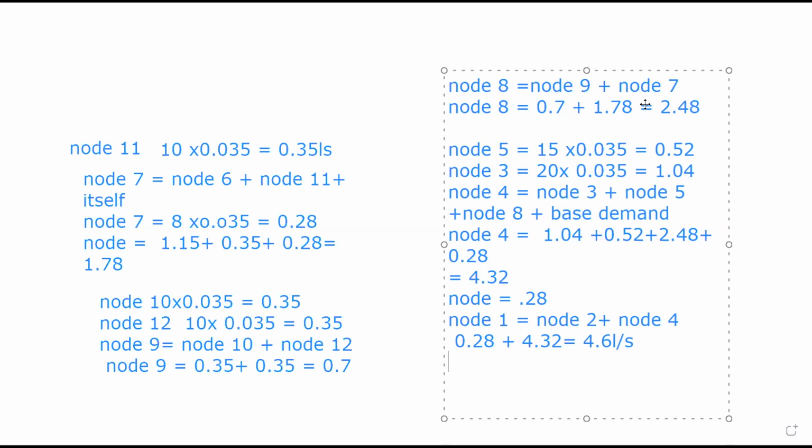The base volume is a percentage of your total volume. These three things are in your manual, in the material I'll share with you. You now add emergency volume. Maybe there's a repair. Maybe there's a pump breakdown. When the pump breaks down, there should be water for people to use for, let's say, 6 hours, 8 hours, 1 day, 2 days, depending on your design criteria.